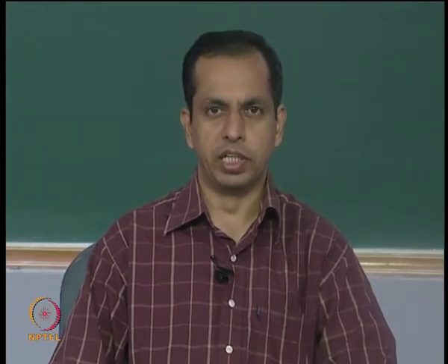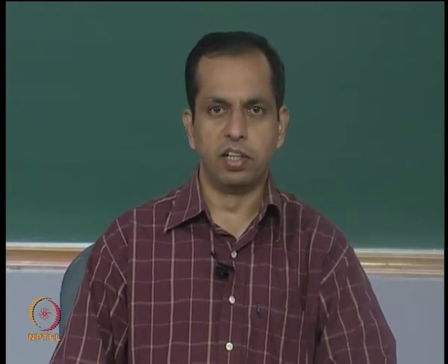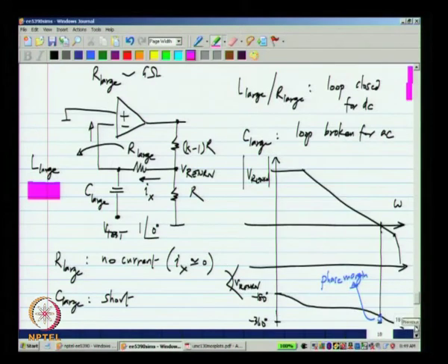But sometimes it is difficult to gauge what parameter of the circuit to change if the transient response has a lot of ringing. Let us say you do the transient analysis, you get a lot of ringing, it may not be very easy to tell which part of the circuit to change to fix this. That is easier if you do the loop gain analysis and also find the gain magnitude and phase through different stages of the circuit, then you will know which part to change. Okay. Finally, there is one small detail that I omitted while discussing this.